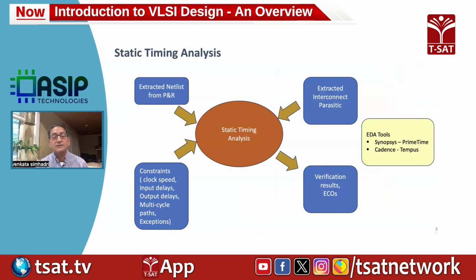That includes the original gates and all the clock trees you inserted. And you extract all the parasitics of the interconnects and feed that into the tool as well. And then you have to define the constraints. This is a constraint file that will have the clock speeds, the input delays, output delays of each input to the design, and